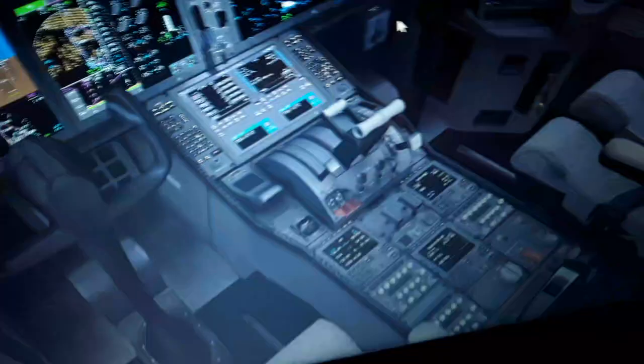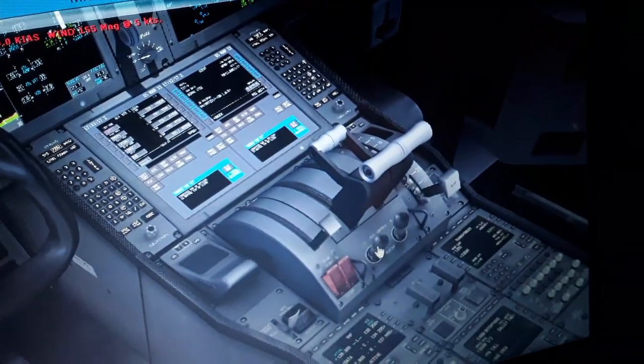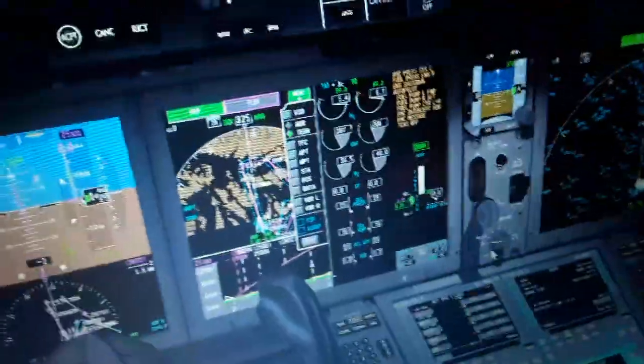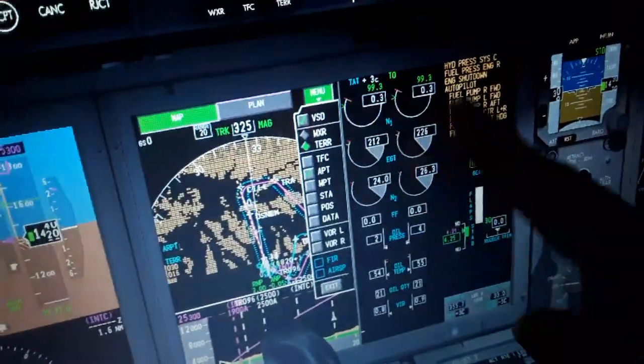So we go in the navigation display and we turn off both engines again over here, both engines to the off position. So you see the fuel flow is off, you see what happens, what it displays. We have the APU on, so you see the faults now.